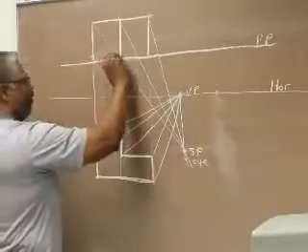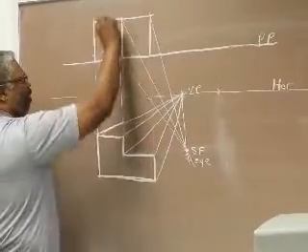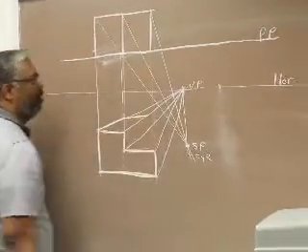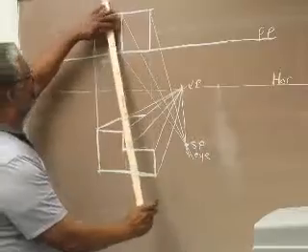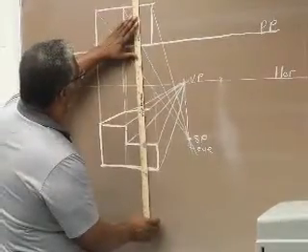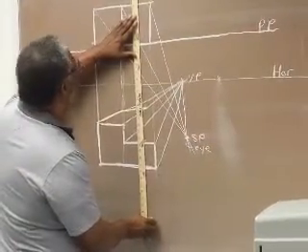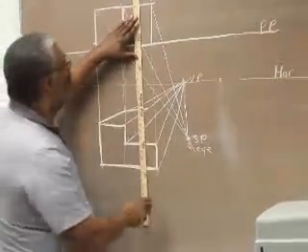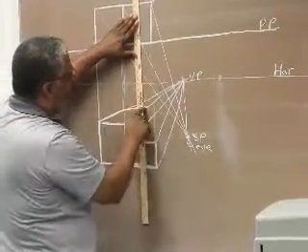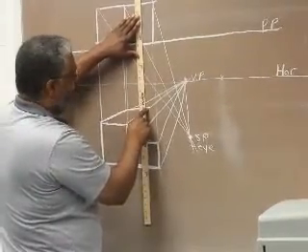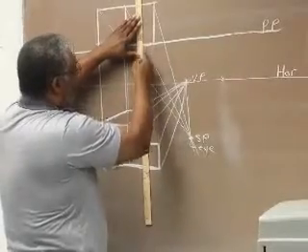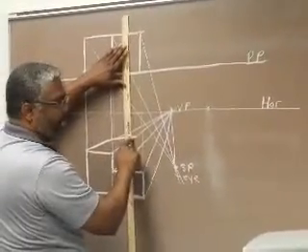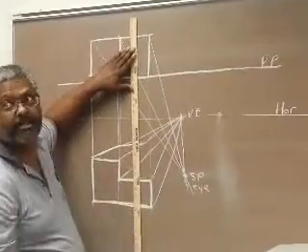It goes right there. My parallel lines that were horizontal lines here remain horizontal, so that would just be a horizontal line. If I take this and go to there, and bring that straight down, it works when you're doing it accurately. When you're not doing it accurately, it's off. But this point here should intersect that point also. So whether I draw this straight down to locate that point, or just take it over horizontally to where it hits this line, it should be at the same point.